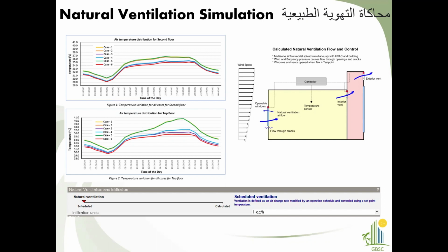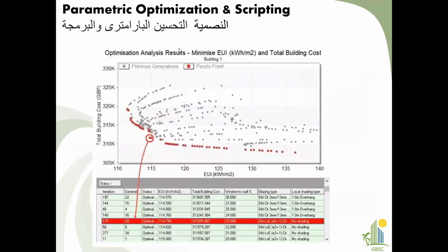These kinds of analysis, the possibilities are endless. Within the natural ventilation mode we can even do mixed mode simulation, wherein we can integrate the natural ventilation with the HVAC system. That is also a possibility that we can look into.